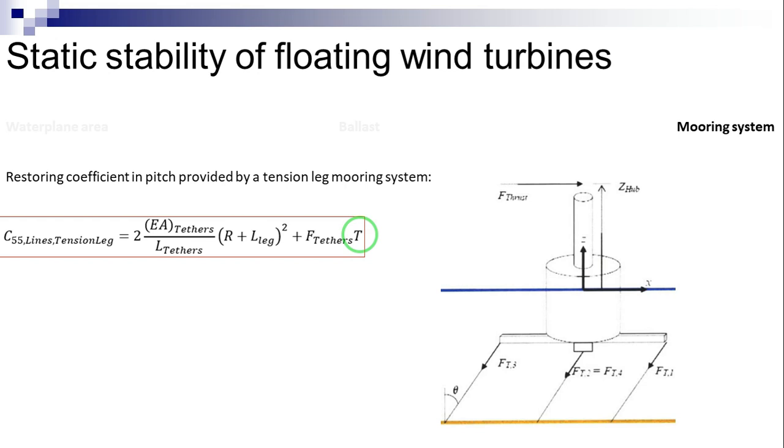Note that considering that assumption of infinite stiffness of the mooring lines prevents any significant motion in pitch, roll, and heave, and the platform's motions are therefore limited to surge, sway, and yaw, or the motions in the horizontal plane. The mooring system must then be designed to adequately limit motions in these modes.